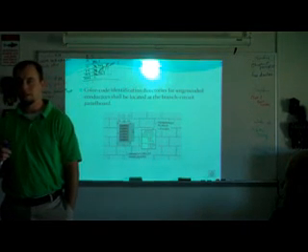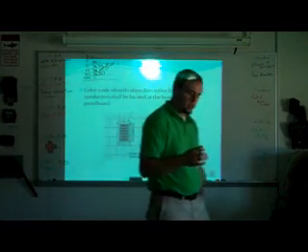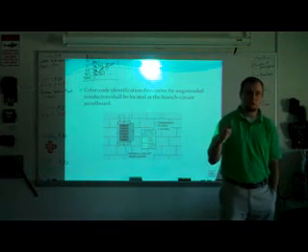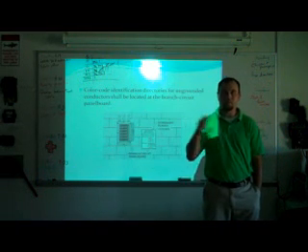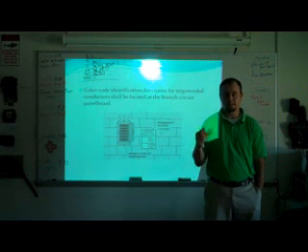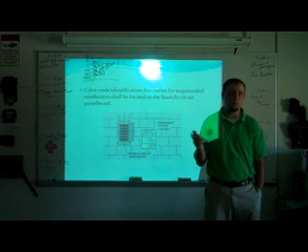Why do they not have a code for DC? Because it's a low voltage situation. When we talk about rules, we're talking about rules on 50 volts or greater. At 50 volts and less, you can pretty much do whatever you want, because it's considered to be safe. So when you're talking about DC voltage, you're talking about 12 volts, 24 volts.